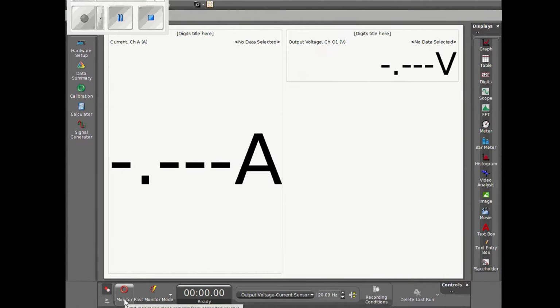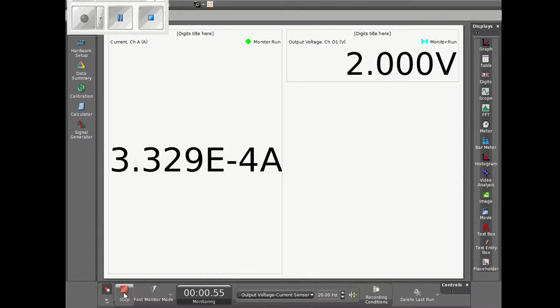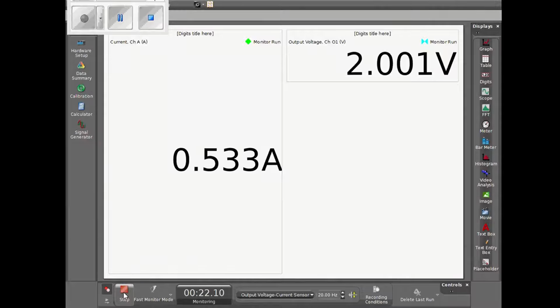So we have the resistance box set to 5 ohms. And let me click on monitor. Now we will touch both sides of the slide wire. One side should give positive reading and the other one should give a negative reading, which means that there is 0 in between. So our circuit is correct and functional. So now we will start sliding the pointer along the slide wire to search for the balance point when the resistance box is set to 5 ohms.